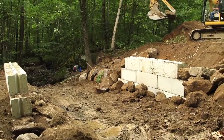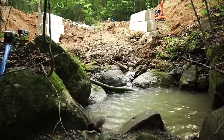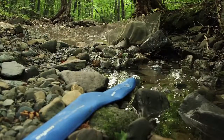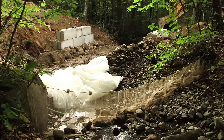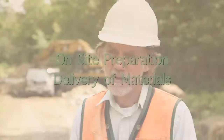Due to the low surface and groundwater flows during construction, a small pump at both the upstream and downstream sumps were adequate for all water control needed. Scheduling construction at low stream flows is ideal for minimizing the difficulty of water control. Note the fish block nets used to keep fish from entering the work area. So primarily, we're keeping the clean water clean, and then any of the dirty water, we try to get it clean before we go back into the stream.